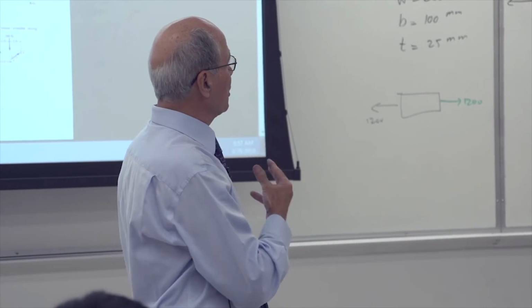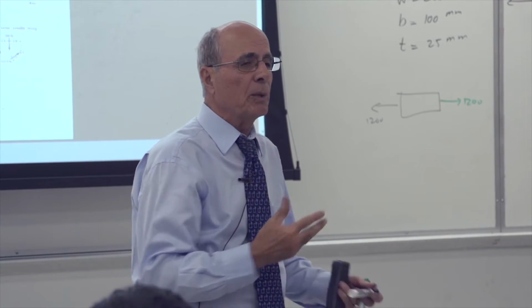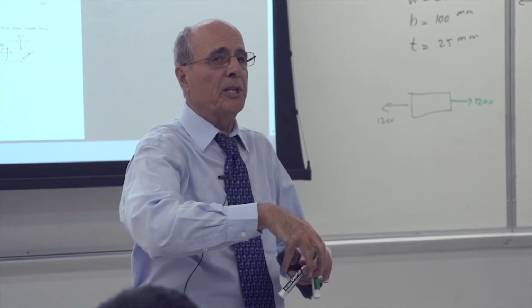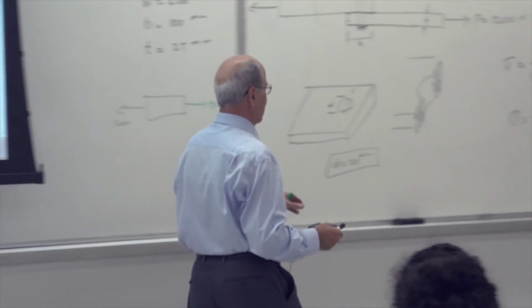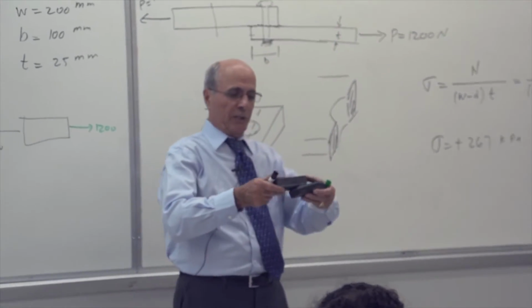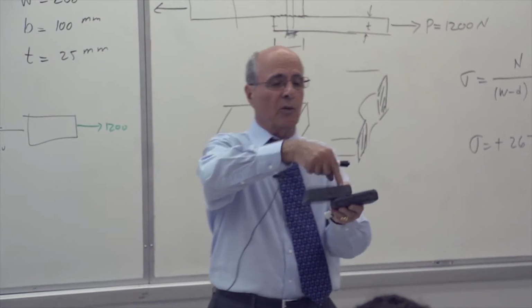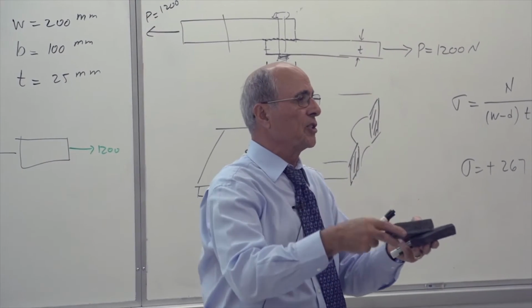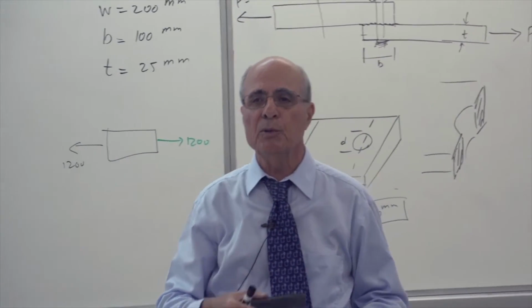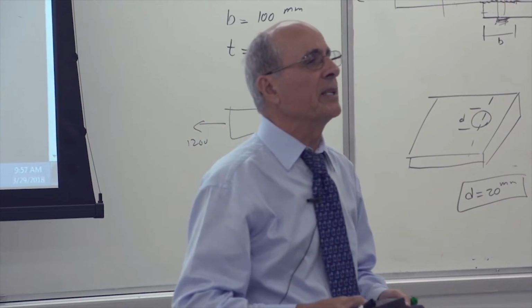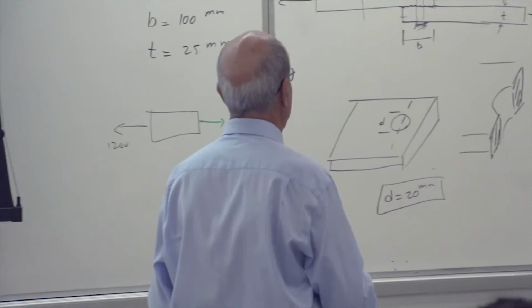Now, what is the bolt under? What's happening to the bolt? If I'm putting a bolt between the two, look at this structurally. Here is the system like that. Here are the two plates. Let's assume there is a nail or a bolt there, in this case a nail because it's a simpler structure, and you are pulling it. What's going to happen is it's going to shear off between the two plates. Is that correct? So exactly that's what you have to apply here.